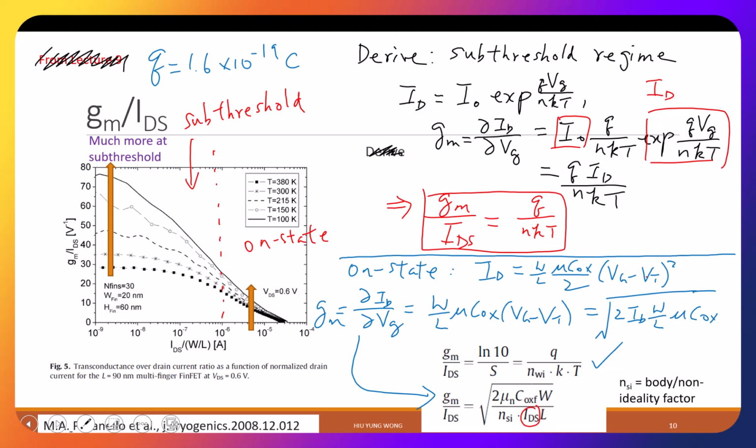But it definitely says that if you have larger Vg minus Vt, the whole thing is not temperature independent. It seems like in that case, yes, you're right. If you plug in, then it doesn't depend on temperature to first order. But of course your Vth is changing, and it also really depends on whether you have velocity saturation or not. Do you still remember?